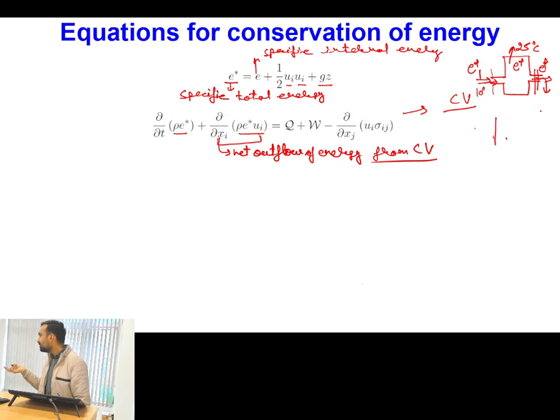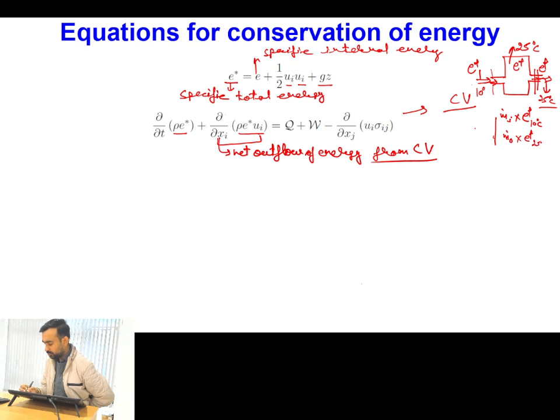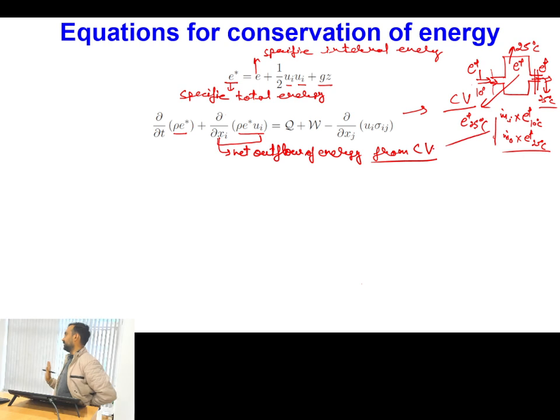It will always be at the temperature within the geyser, within this control volume. So say it will be at 25 degrees Celsius. Now if you have to write the total change of energy across the boundary, then you will write m dot inlet into energy corresponding to 10 degrees Celsius as inlet energy, and outlet energy as m dot o into energy content corresponding to 25 degrees Celsius. And the energy within the system will also correspond to 25 degrees Celsius.